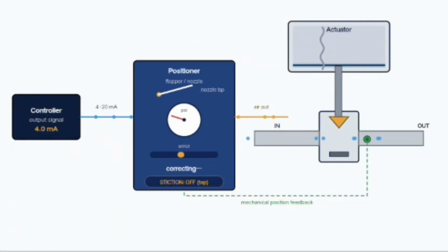Control valve in the control loop. The control valve is one link in a closed loop. Understanding its place helps in troubleshooting. A control problem is often not the valve itself but the transmitter, controller tuning, or air supply feeding it.